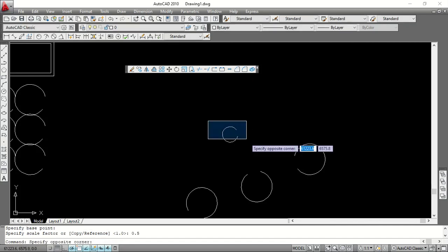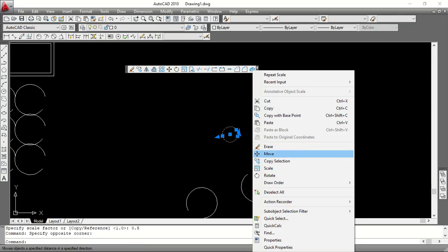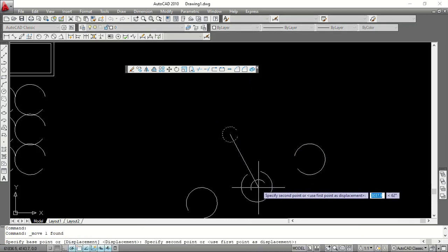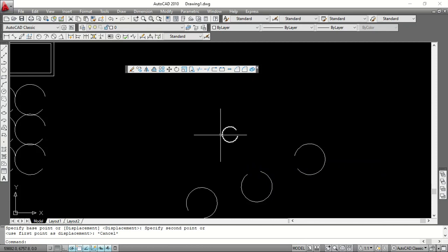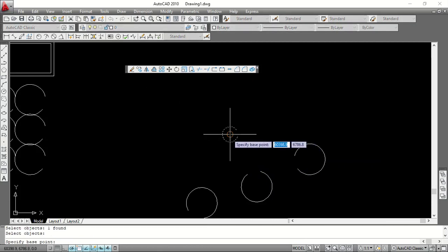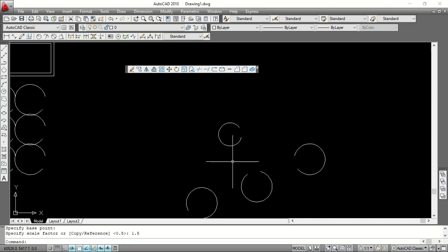So this is half of the initial object. You see, it's small. Okay. If I want to take this back, I go back to this, select the object, right click, select the center point, then give me 1.5. Enter. Okay. So this is how you can play with all of this.